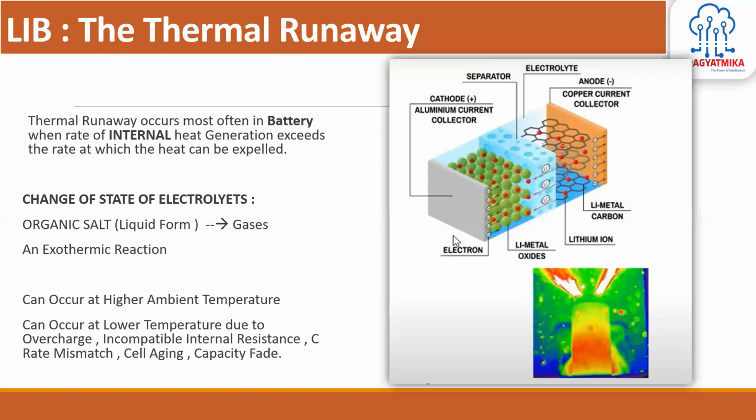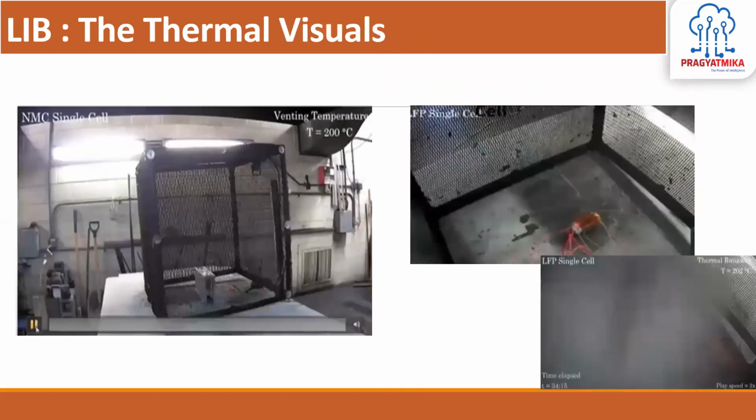Even in a colder environment, even in winter time, if you are not following the proper procedures, your cell can burst. So it is agnostic of the ambient temperatures. There is more of an impact in the case of higher ambient temperatures: the rate of production of gases goes higher. But I don't limit you to only the higher ambient temperature zones. It can be at lower temperature zones, and the cell health loss is more at lower temperature conditions also.